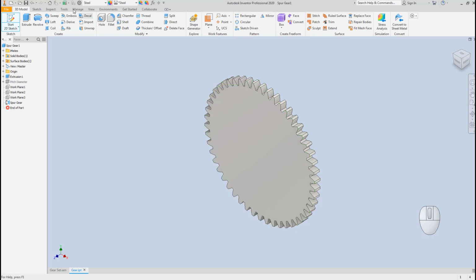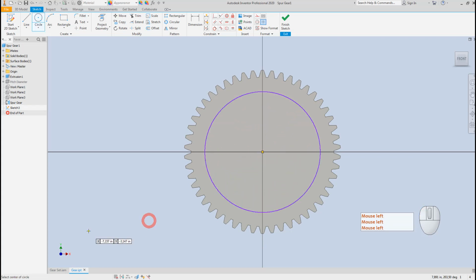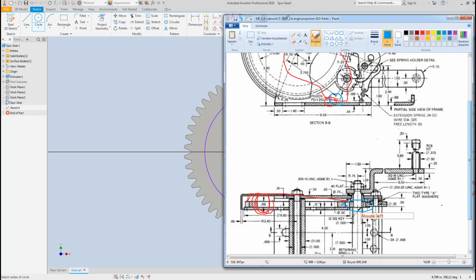this body shape inside. I will just create a flange here, and make this with cut extrusion processes for need. This time I need a sketch on this one, and I will just create a circle to cut here. And from the top side, for example, let's make our first gear for the other assembly. As you see, I will take my mouse back.